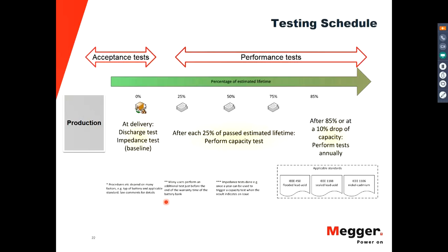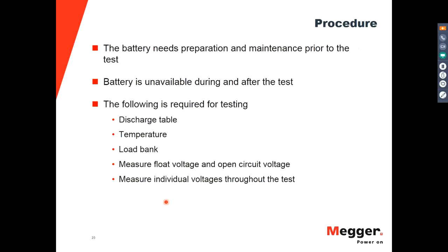It's the same with insulation tests. If you apply a very high voltage to an insulation that is not rated for that voltage, of course you're going to break down the insulation. So it's a matter of good practices and good handling of the test and the elements that you use for the test.